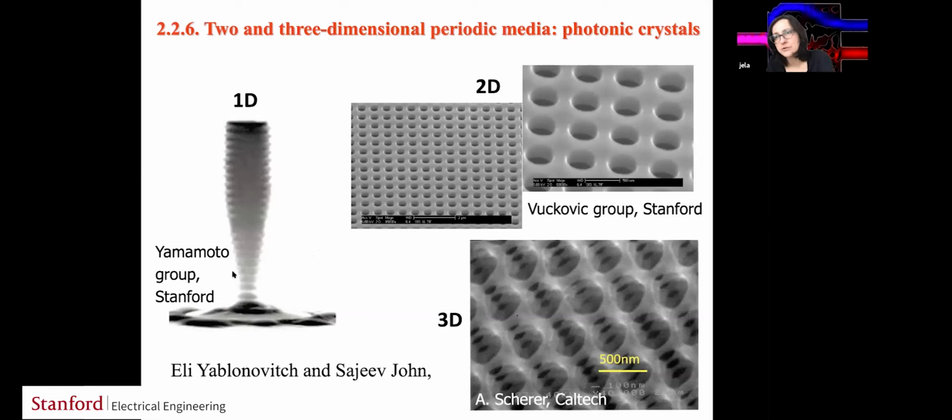So it turns out that you can decompose it if you know that your electric field confinement in the XY plane is something like a Gaussian. You can calculate the effective index for all the layers of the structure and reduce that to a one-dimensional periodic structure problem. Then you use the one-dimensional master equation to solve for the band gap, or you use the transfer matrix method. And then your final field is the product of whatever you solve from the one-dimensional periodic structure and the confinement in the other 2 dimensions.